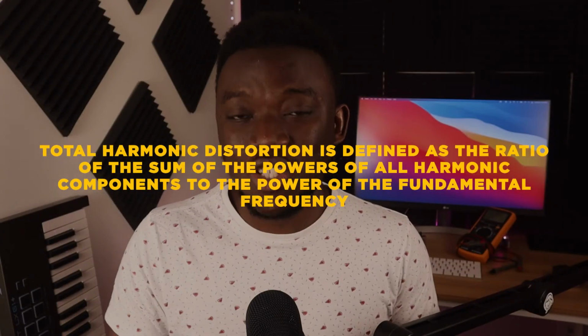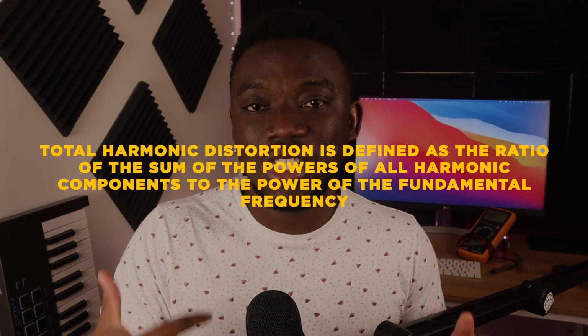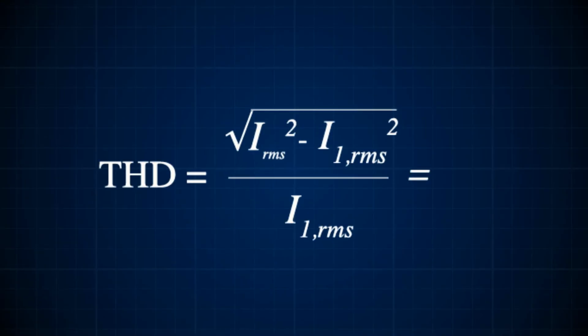Now if you're not too sure of what THD means, it is defined as the ratio of the equivalent RMS voltage counted from the second harmonic over the RMS voltage of the fundamental frequency. Now if you're not too sure of what that means, you'll find a link in the description of this video to another video that explains it very well. So basically the equation for the total harmonic distortion is the square root of I squared RMS minus the square of the RMS current of the fundamental frequency, all divided by the RMS current of the fundamental frequency. When we take a look at this equation, we have all the variables except the RMS current of our fundamental frequency. We would need to take a look at this graph.